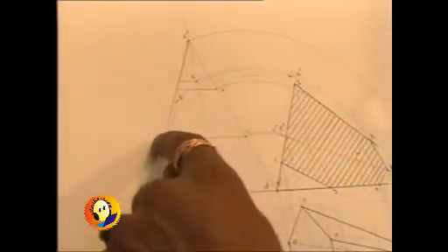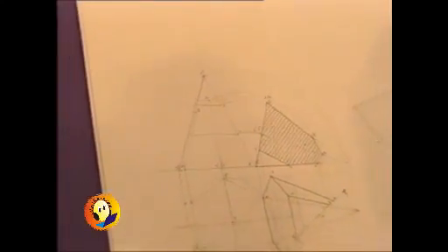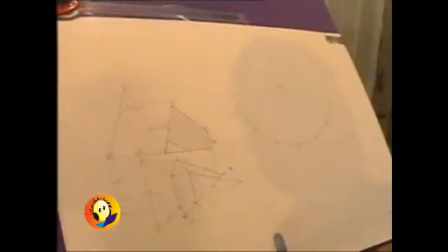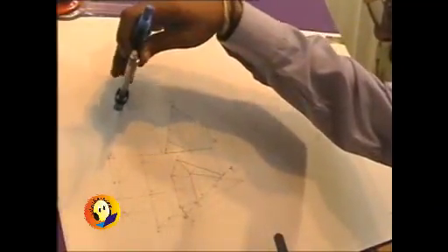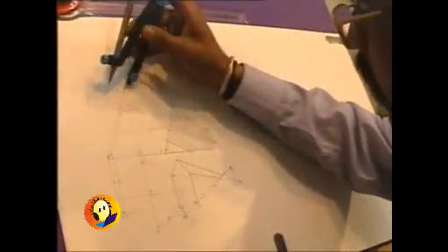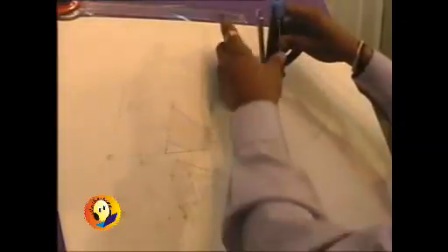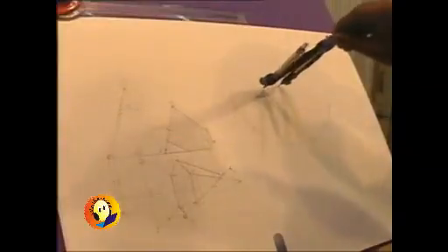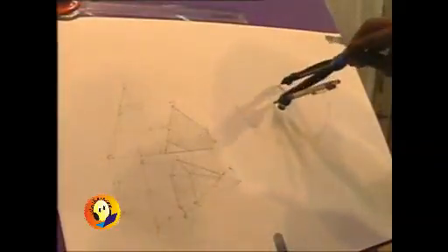So observe that I have transferred all the points to the true length that I have already found out, and then taking that particular true length in the compass, I am required to transfer all the distances, that is from V up to 6, measure the distance, and from V on the development you mark it, or you can draw the arc corresponding to that. Then for point 4 I am just going in sequence as they are present over there. So point 4, then we have point number 5, even that can be transferred. I am drawing it by arcs.